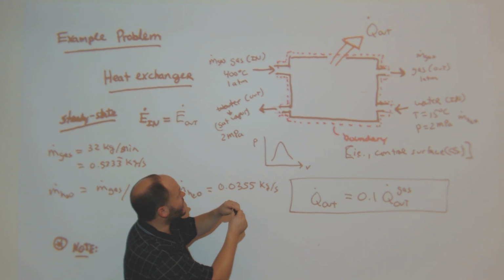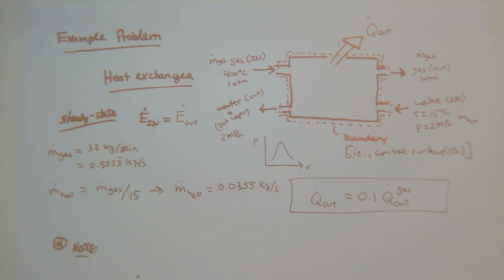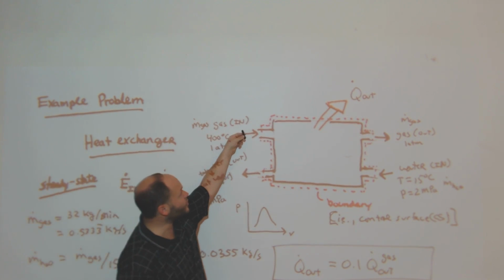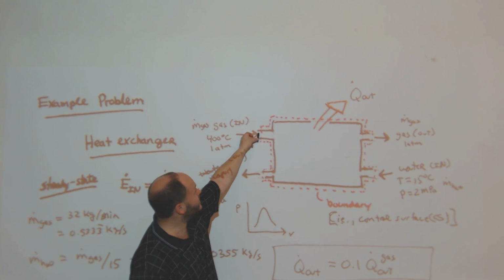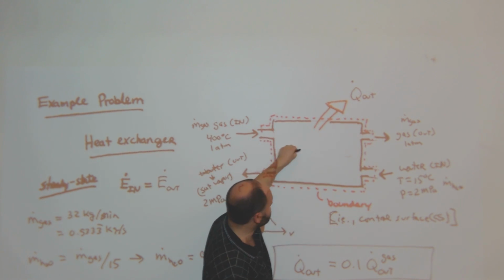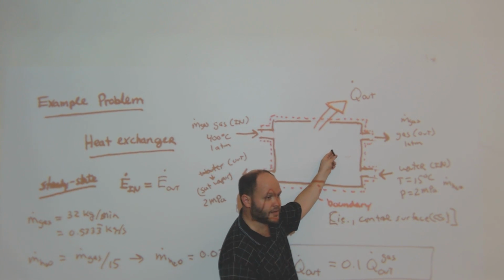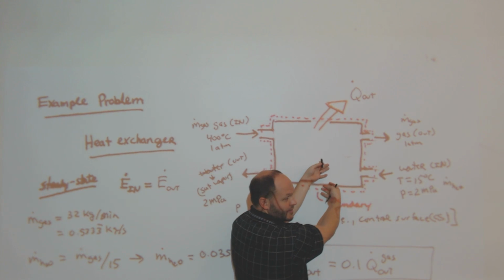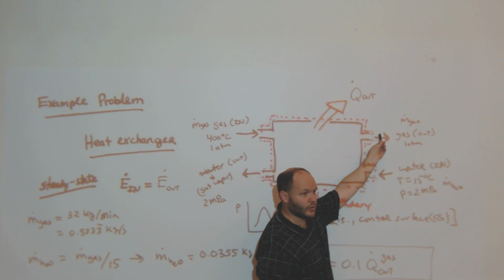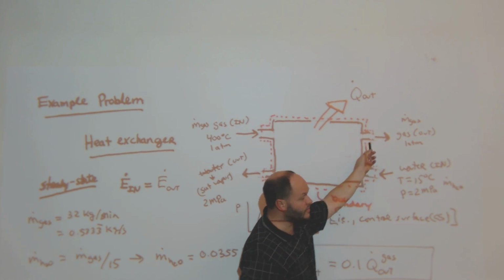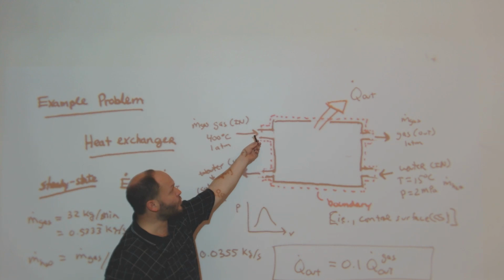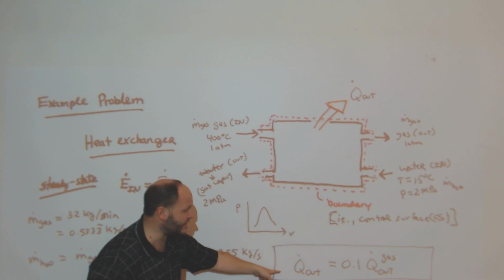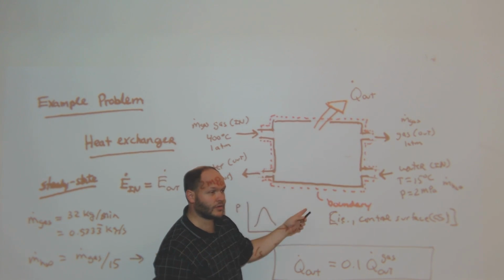So if I were to look at it, I'll move this down for the sake of analogy. So I have, this is my control volume of the gas coming in. And as it comes through all my piping and stuff like this, its temperature is decreasing. And so there has to be heat loss out, and it's going to the water into the heat exchanger, and then it leaves at a lower temperature. And so there was some rate of heat loss from my gas passing through, and that is a percentage of the total heat out.